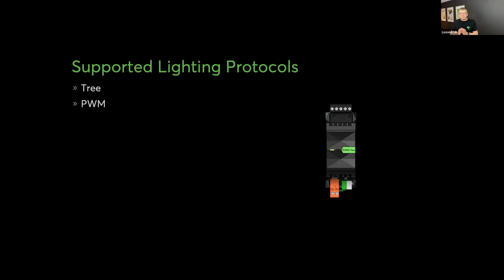So if we're then dimming on the mains side and then relying on a transformer in the middle, that's why you're not getting necessarily a great dimming curve. But dimming on the actual LED side, on the DC voltage, you'll get that much smoother dimming.